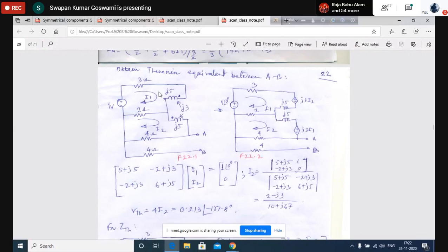Okay, তাহলে এখানে একটা সার্কিট রয়েছে, two inductors which are mutually coupled, value দিয়ে রয়েছে। So 1 volt is a sinusoidal source with instantaneous positive polarity here, instantaneous negative polarity here. Impedances are J5 ohm self impedance, J5 ohm self impedance, আর এই দুখানা ইন্ডাক্টরের মধ্যে J3 is the mutual impedance. Okay, J3 is the mutual impedance.